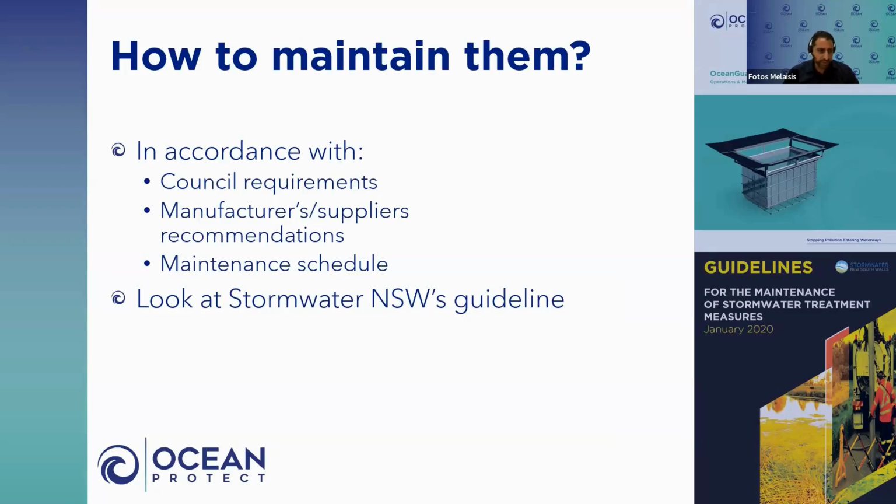But in terms of pre-treatment, I'd probably look at assets such as the pit insert. Gully pit baskets, you typically have a graded access cover that can be opened up. You can remove the debris from inside that basket. The actual filter liner itself can be washed down or hosed down, depending on if there's any occlusion in that fine filter fabric. And GPTs, similar kind of thing.